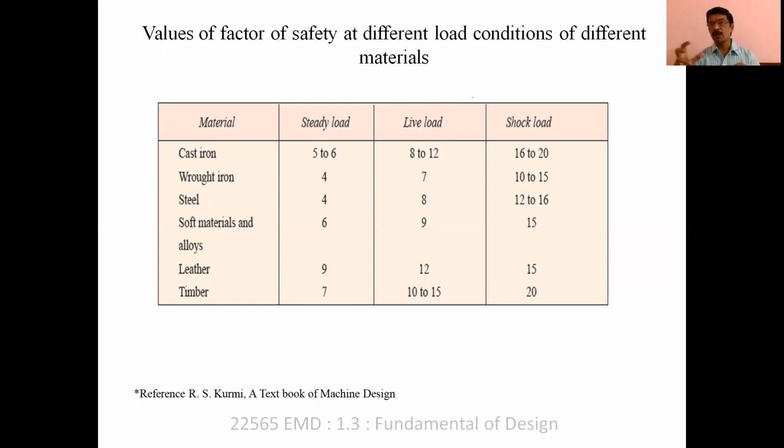If there is shock loading, again there is more risk, so the factor of safety is going to increase. If you think about the working stress, in steady load condition the working stress has a higher value, live load has an intermediate value, and in shock load condition the working stress value is very low as compared to steady and live load.